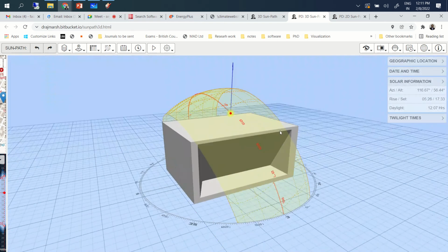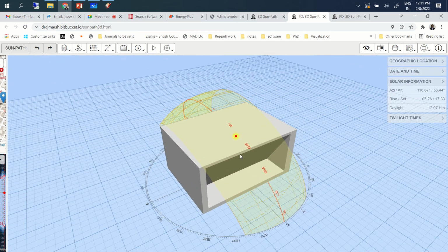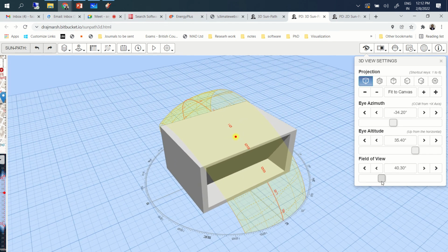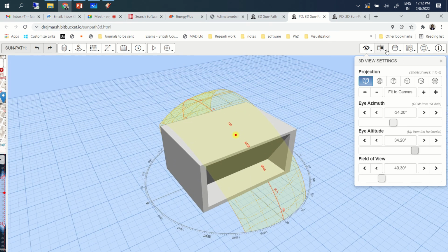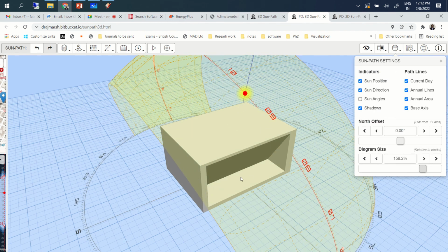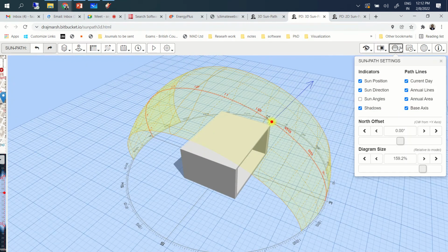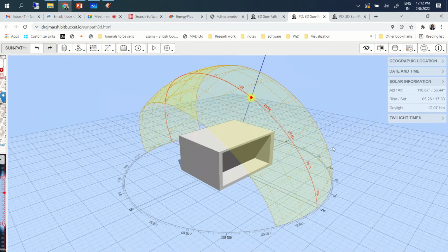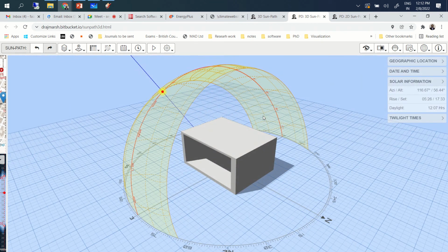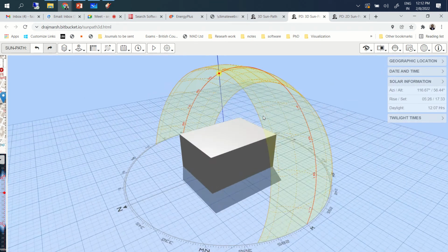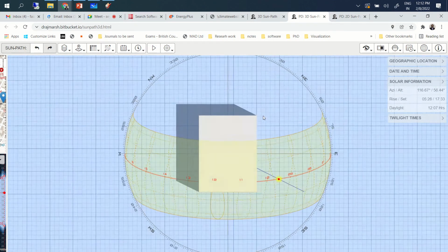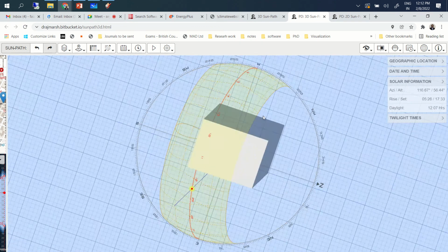Okay, now we have the model and we have the sun path diagram with us. And if you want to specifically modify north, at the moment you can operate these things using the numbers: 1 for rotating, 2 for axonometric or isometric view, 3 for plan, and so forth.